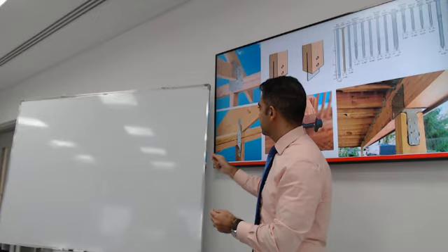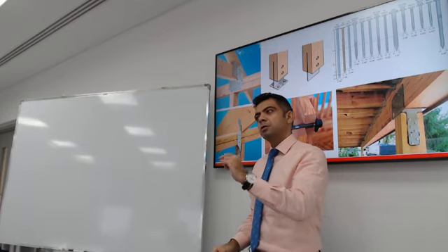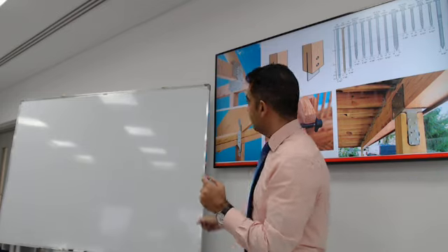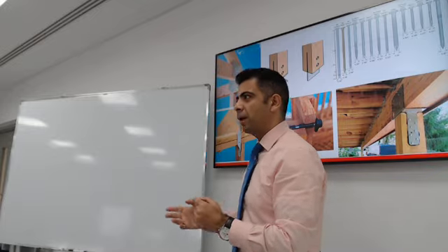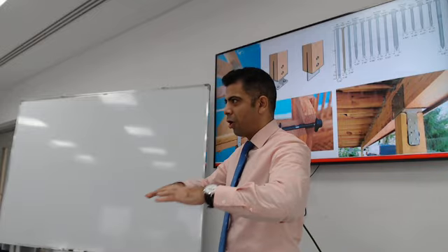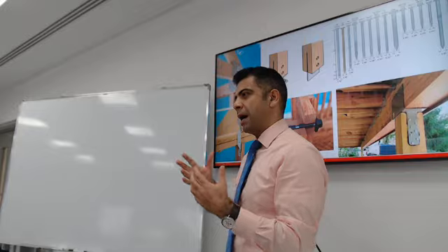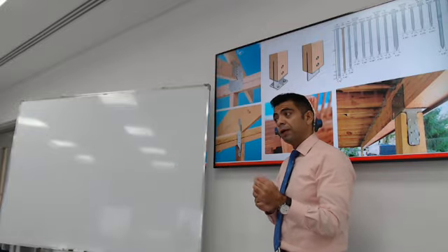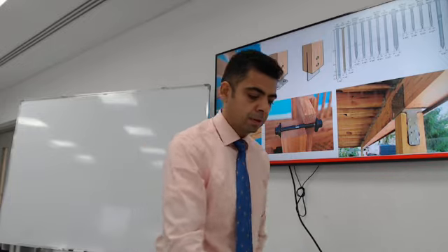This is obviously something to think through when you're designing different types of structures with different construction materials. Because if you are designing a building from concrete, are you worried about the self-weight of the concrete floor being sucked out of the building because of a storm? The self-weight is super high. But when you get to wood, wood is relatively light compared to its strength. That's why it's attractive as a construction material.